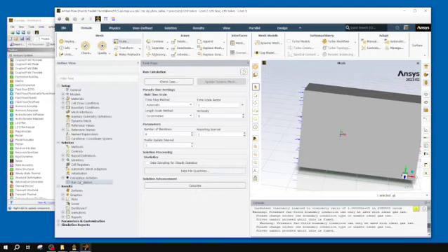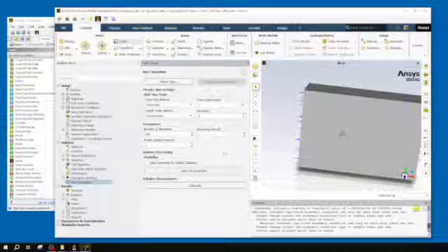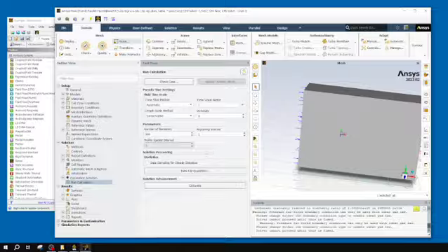And I'm gonna change a couple of these. Number of iterations is the first one I'm gonna change. This is gonna be your total number of iterations that it'll compute. I believe I want something like 500, should be more than plenty. I'm gonna have a profile updated every time, but I'm only gonna have it report it every 5 iterations. I just don't need it to tell me every single number. So I'm increasing that to 5 for it.